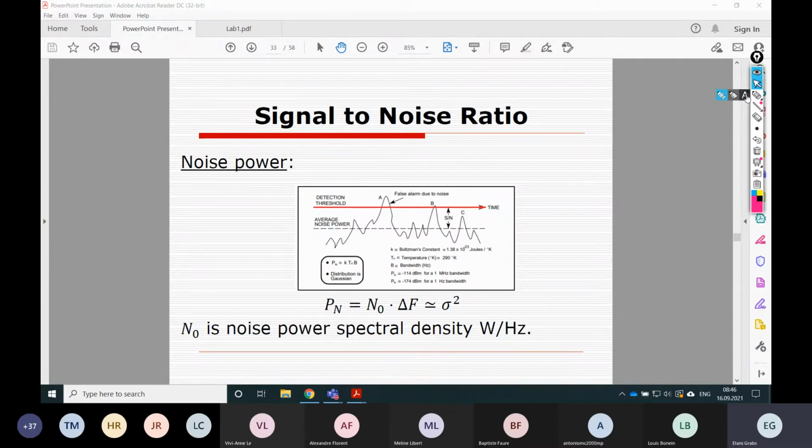The noise power can be evaluated from a noise density and noise frequency band. Now, we already discussed that this noise band is infinite. So instead of the noise band, we take the band of our signal, because that is actually the only place where this noise matters. So imagine the situation: you have this noise density, which is infinite and very small, and you have some signal, which is strong but has a narrow band.